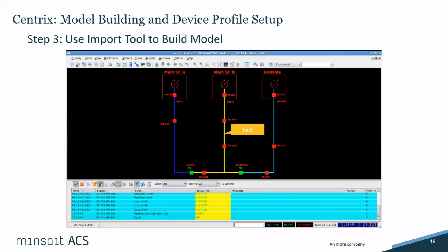So with this, what we're just quickly showing is a fault on that middle feeder in between those two devices, and watching how first we are going to look for where that fault is. We receive the indication that we've got a trip to lockout. We know where it is, so we start to isolate that faulted area.